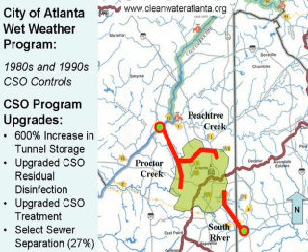And then there's a couple of multi-use technologies looking at innovative ways to try to treat both dry and wet weather treatment systems, maybe expanding the biological treatment, as well as treating peak wet weather with high-rate treatment. And then in the end, we will talk about disinfection, how designers look at disinfection and come up with design considerations, and then how you take that data and show compliance with water quality standards like TMDL requirements.